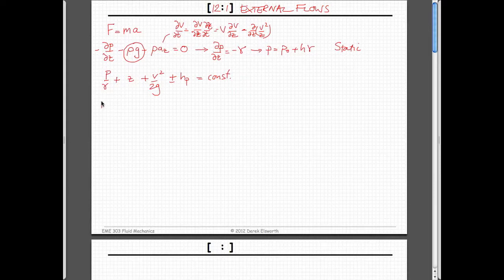So if we call this pressure, if we call this elevation head, if we call this inertia, and if we call this viscous loss, you remember we did a few things with these. So this is this course in 10 minutes or less, basically. We looked at the ratio of the inertial forces to the viscous forces. And so this was inertial to viscous forces. And that came out to be a number which was a velocity, a density, a length scale, and a viscosity, with the viscous forces on the bottom. And we said that was kind of important in some of the things that we deal with.